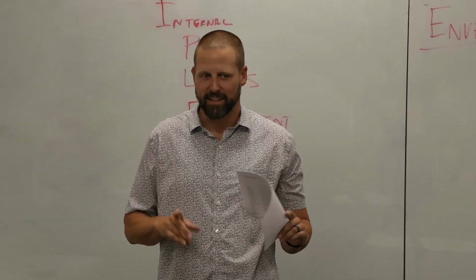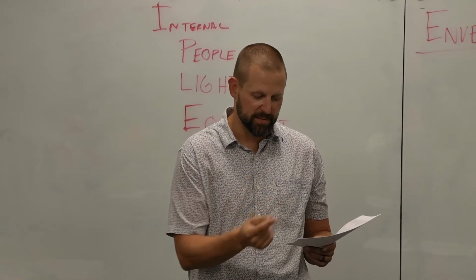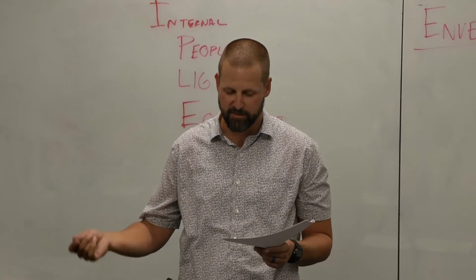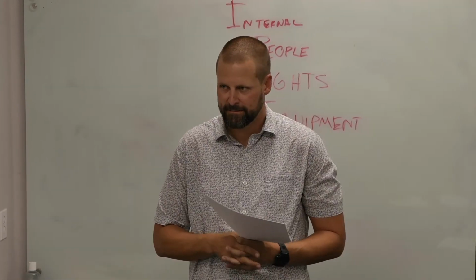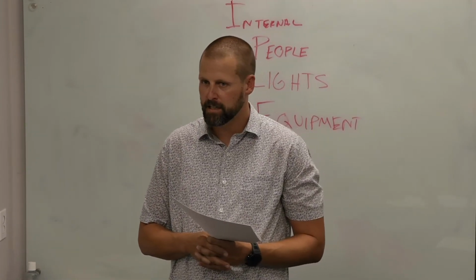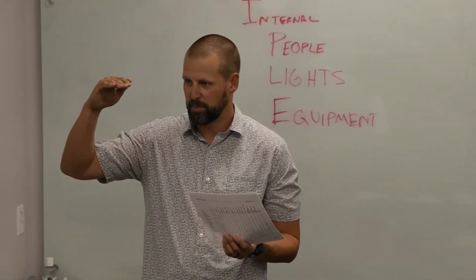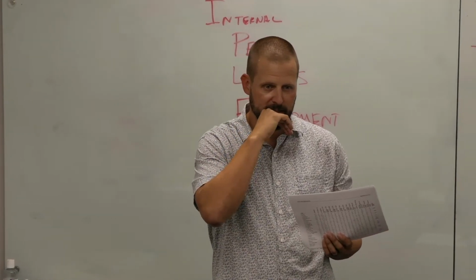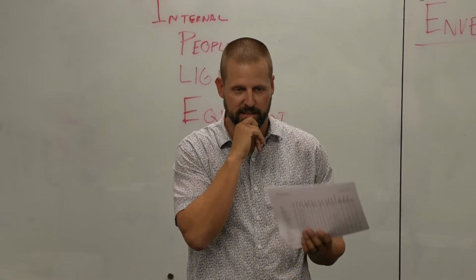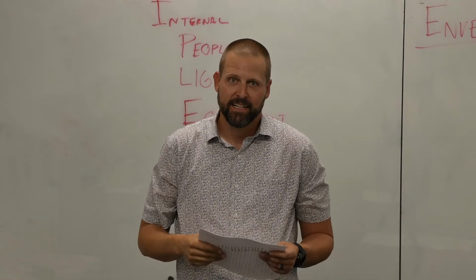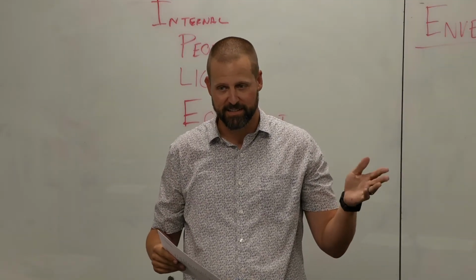But before I get into that, does anybody know where we use the 0.1% versus the 0.5, 1, and 2%? Like how do we decide what to use? Good guess. If we went to the desert, we'd pick a city in the desert and the weather would go up. Yeah. So critical applications. So engineering judgment: if it's critical, you want to use the most stringent design because it's got to stay up.